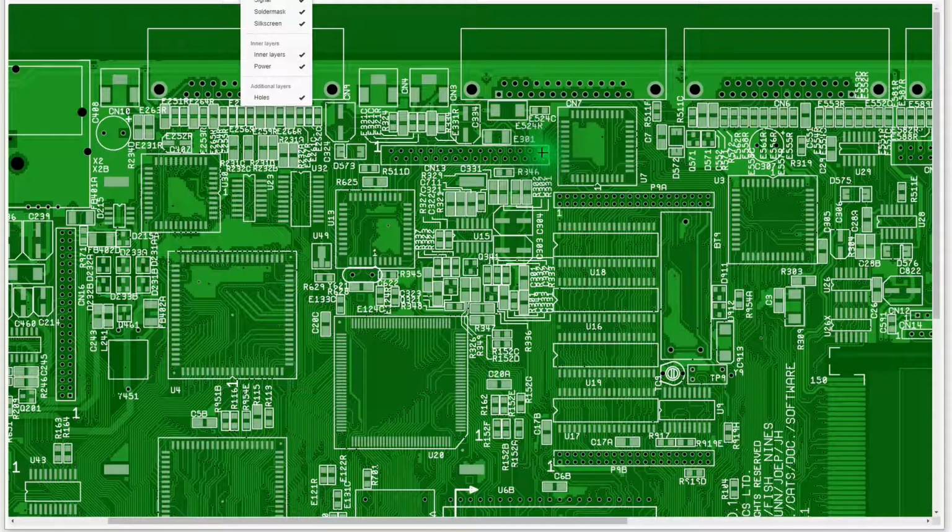If I'm to approach this, I would unsolder all the pins. I would go in and wiggle every pin and make sure it's absolutely loose from the sides of the via. The pin is just floating there. And in that state, that connector should just basically fall out. When we get to a later video or actually get on the board, we'll do this.